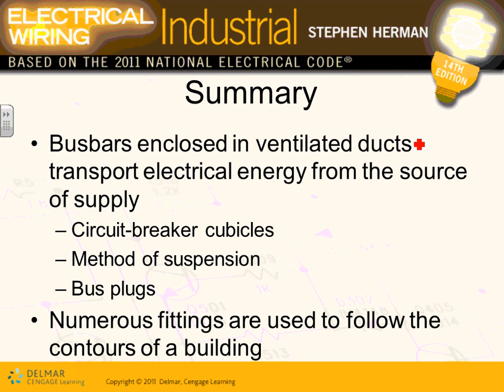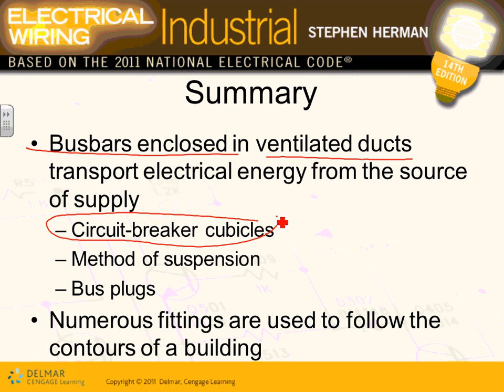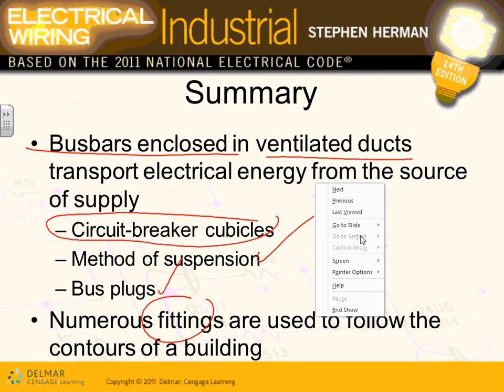Okay, any comments, guys, any questions? That's basically it. Summary, bus bars, ventilated. You put a bus bar sandwiched together, enclosed in a ventilated enclosure to carry energy. They can supply circuit breakers. There's a lot of methods of suspension. There's a lot of plug-ins. There's fittings that you have to pay attention to in order to move the system through the three dimensions inside that building.